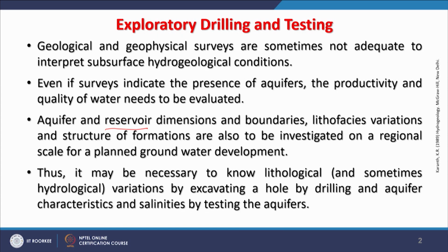Therefore, it is necessary to know lithological and sometimes hydrological variations by doing this exploratory drilling, by excavating a hole by drilling methods, and to acquire formation characteristics and information about salinity.